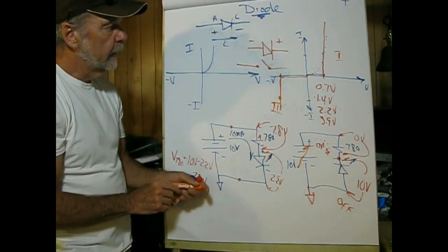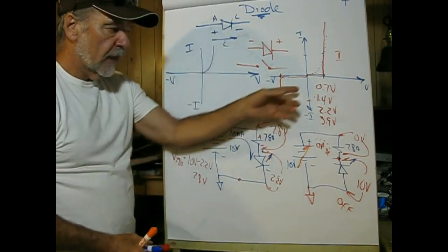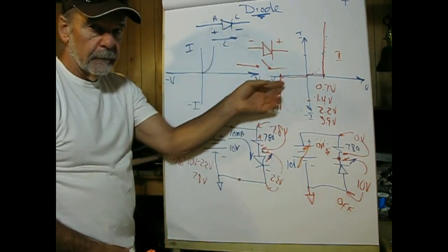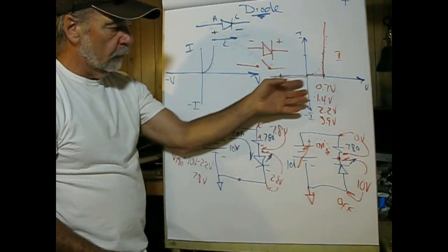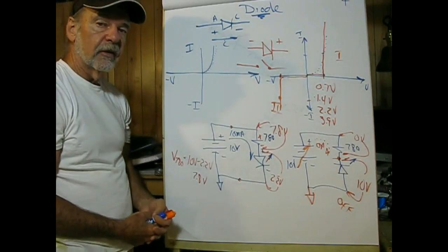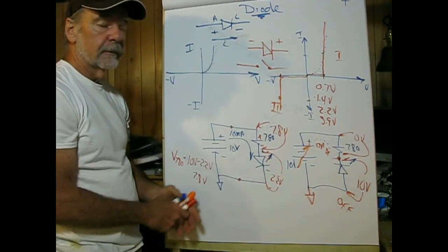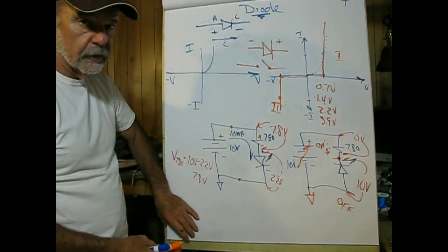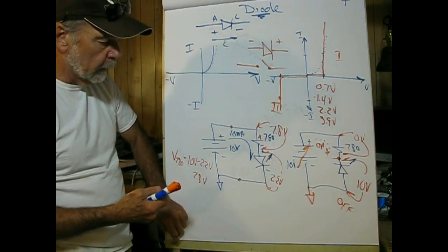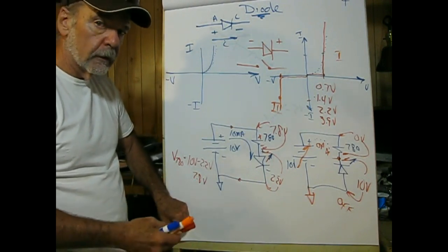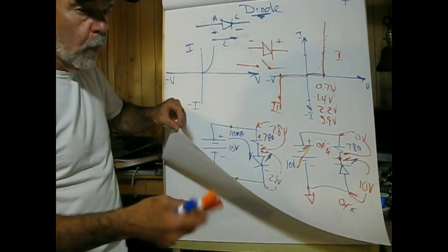But a light emitting diode or a conventional diode is not designed to operate in breakdown. So much so that LEDs typically are specified with a reverse voltage rating of 6 volts. Their purpose in life is not to block voltage in the reverse direction. It's to take electrical energy and convert a part of that into light energy, and that's called efficacy. It's like efficiency, but the quantities aren't the same.